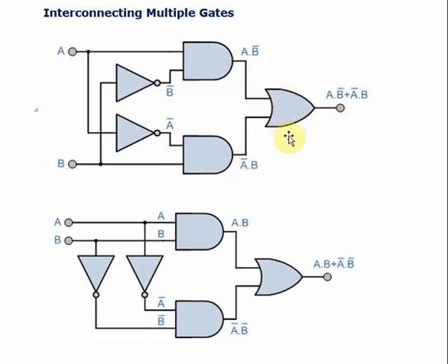Now what is this gate? OR gate. OR gate is a summation, no? So now the input is this, right? It is not one digit; here this is the combination of this signal. Now this only we are feeding here. Therefore we need to feed A dot B bar, OR. What is this gate? OR, so here you need to place OR. Then this one, what is the next input? A bar dot B. OR A bar dot B. So if you can write this with clear understanding, you can write the output for any kind of logic gate, right?